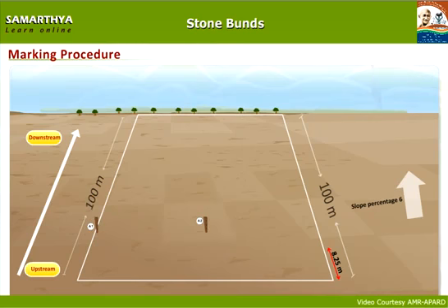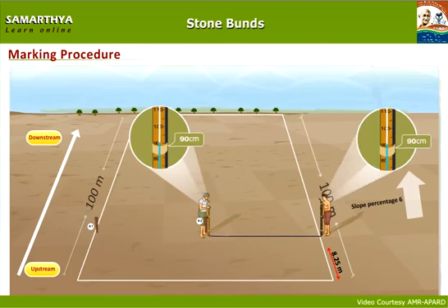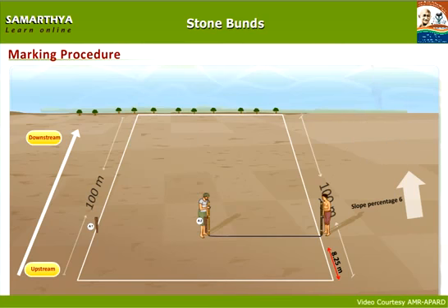Now place the first end of the marker at A2 and stretch the other end, and adjust the instrument till water levels are found equal. Mark this point as A3. Continue this process throughout the field. Now, join the ground-driven sticks with a thread and draw a line using chalk or lime powder.